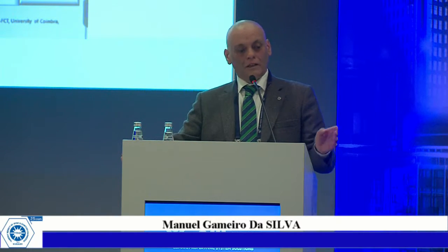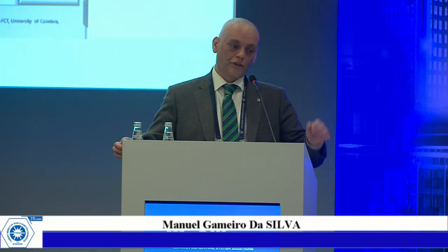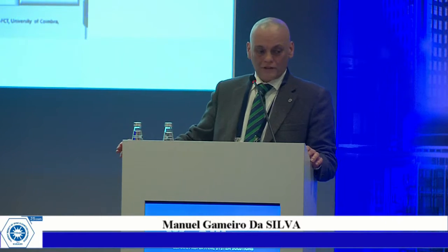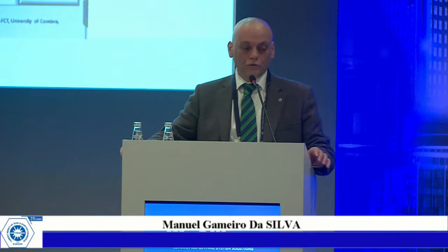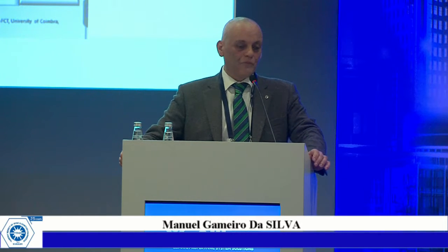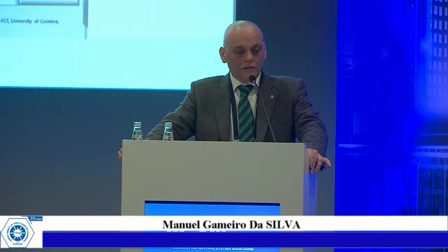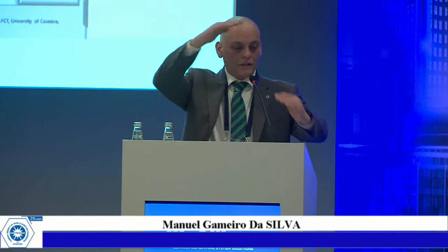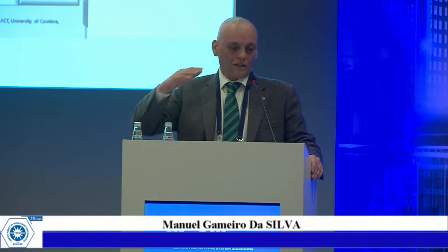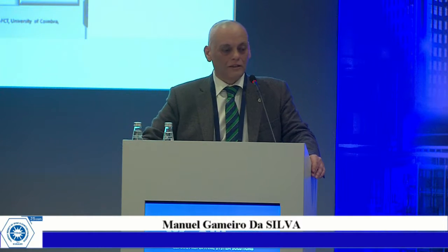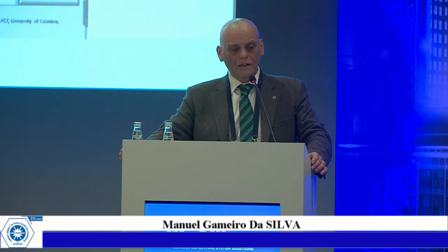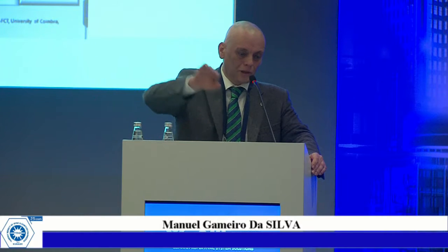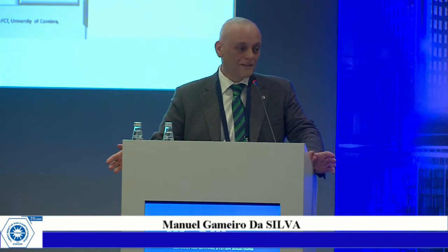And this is the adaptive model. So we have the indoor operative temperature as a function of the running mean outdoor temperature. Of course, this area is according to the Dutch law. So we have the comfort area, and the red line is the optimal situation. So we have 2 steps. The upper step in the red is the summer situation, and the other step is the winter, and in between we have, let us say, the mid-seasons.